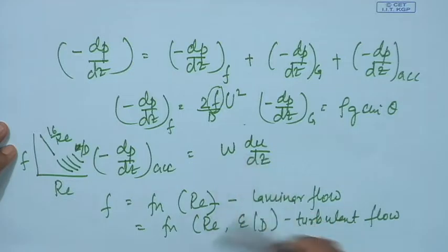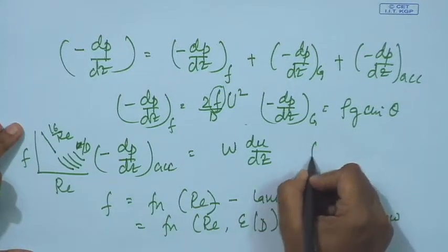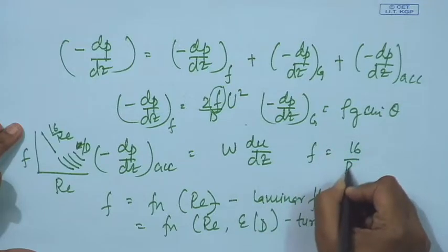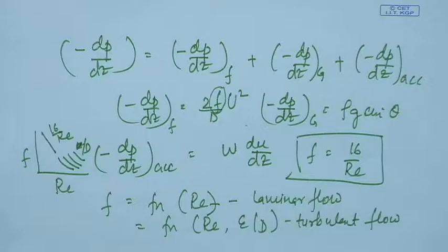So, therefore, it is quite expected that our life should be much simpler, because in this particular case the relation f = 16/Re should be applicable. But at the same time, we have seen how much wall wettability and wall roughness affect both the flow patterns as well as the void fraction and other hydrodynamic parameters in microchannels.